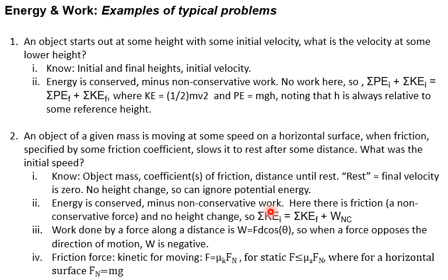For the friction itself, keep in mind that if it's moving, you use kinetic friction: the kinetic coefficient of friction times the normal force. If it's static, remember that the static friction force is less than or equal to the static coefficient of friction times the normal force. And remember that for a horizontal surface, the normal force is just the mass times little g.